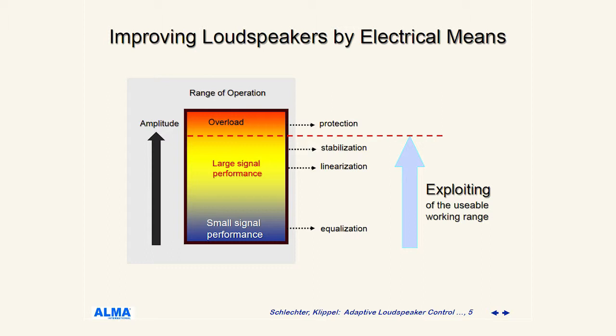Like that, we could exploit the usable working range and get more out of the physical resources of the speaker. If you get really to the limits, you might need some means for stabilizing the loudspeaker. And certainly there will be some hard limit where you shouldn't drive the loudspeaker beyond, otherwise it will get damaged, it will be destroyed, and you need a secure electric protection system for avoiding the loudspeaker getting damaged.